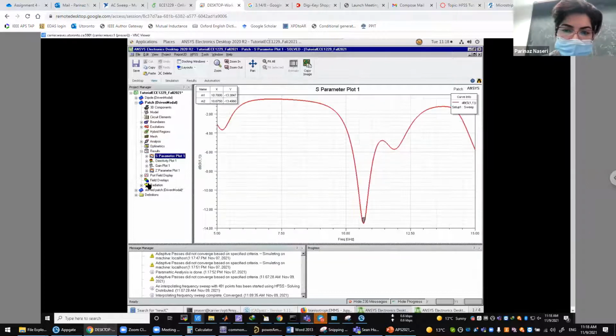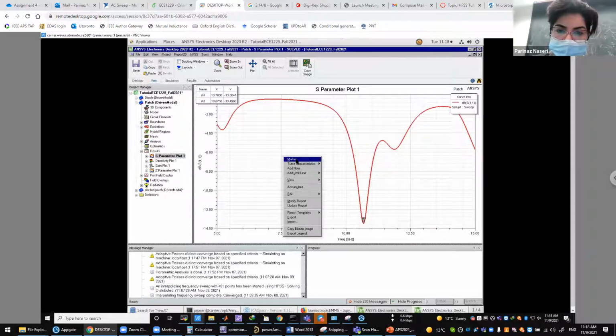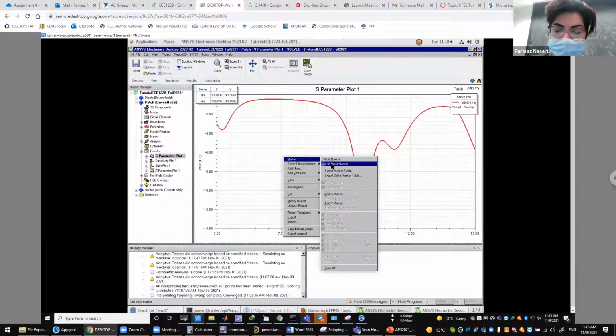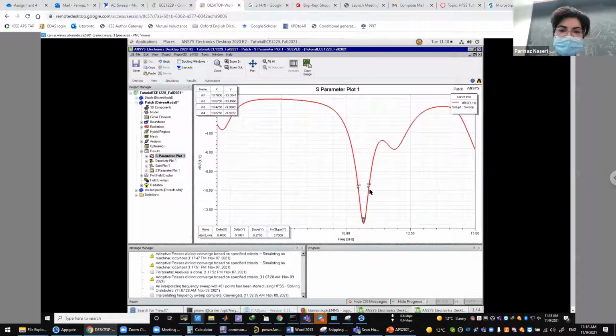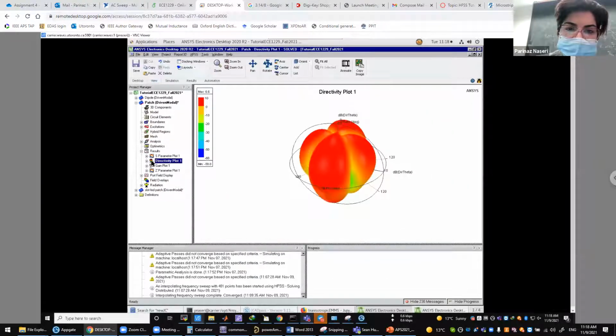For some reason, okay, yeah, this patch antenna, for example, is very narrow band. Like a single patch that I designed here. It's very narrow band, right? If you go with the 10 dB bandwidth here between M3 and M4, then you only have 400 megahertz of bandwidth. And then also the gain, I think, is about 6 or something.